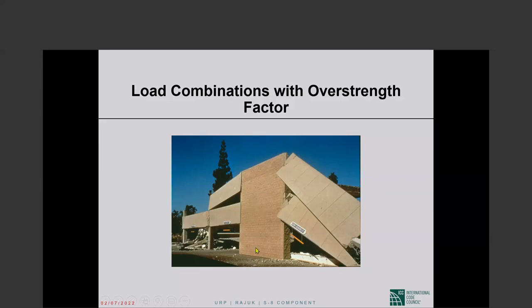But as we approached the building, this shear wall looked really incredibly good. It not only was standing up, pretty much nothing had happened to it, not even significant cracking. And the question immediately arose, how come the rest of the structure is doing so badly and the shear wall is so much better off? And the answer that emerged pretty quickly is that